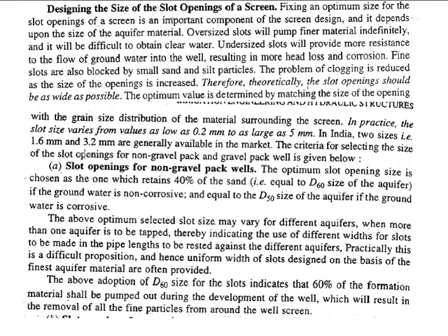A slot size between 1.6 to 3.2 mm is generally preferred in India. And if you take a wider view, then a minimum of 0.2 mm and a maximum of 5 mm size is preferred. Next we have the basic criteria for selecting the size of the slot opening for the non-gravel pack and the gravel pack well. If we are going for a non-gravel pack, what should the slot opening be, and if we are going for a gravel pack, what should the slot opening be. We will see both of these cases one by one.